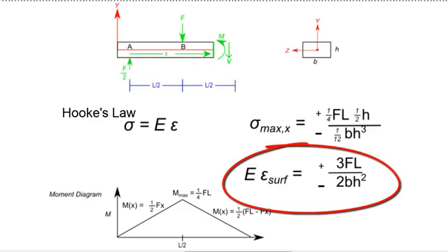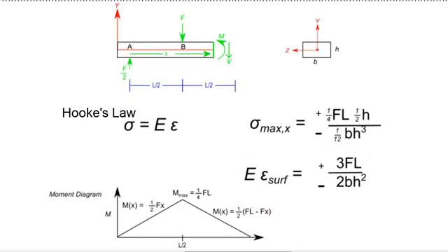While this is a relatively easy test to set up and analyze, there are some drawbacks to using three-point bending. For one, the roller used to apply the load also causes a stress at the point of application, and this can cause premature failure. This risk is amplified by the fact that the point of application occurs exactly where the peak bending stress is also generated. It may also prove difficult to place a strain gauge exactly at the point of maximum stress, a matter that is complicated by the fact that there is non-uniform strain on each side of the applied load.